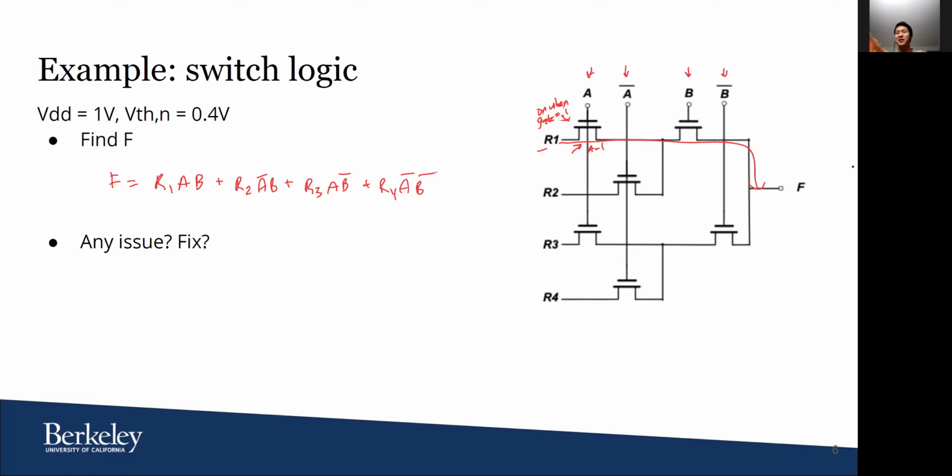Isn't this almost a mux? Yeah, that's it. If this circuit were a logic gate, this would actually be a 4-input mux, where the inputs are R1, R2, R3, and R4, and then the mux control pins are A and B. Those would be the 2 bits of the control. Very good. So now, given this circuit, can you find any issue with implementing a 4-input mux this way?